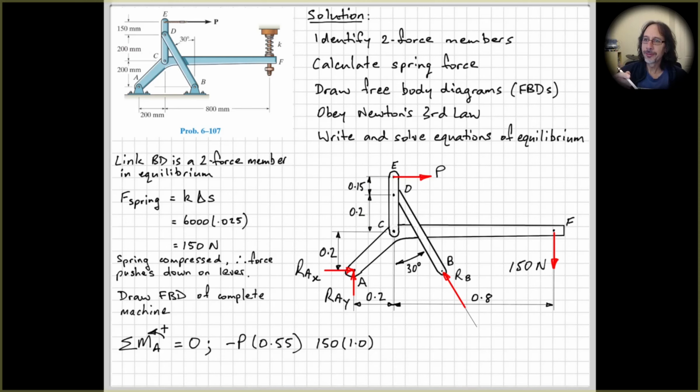So next, looking at the spring force out on the end here, we have 150 newtons times its perpendicular distance, 0.2 plus 0.8 equals 1, so put in 1 here. So even though the number that we're putting in here is 1, and it doesn't change the 150, get into the habit of actually putting in this distance that we're using, just so it's easy for the person reading your work to see what's going on in your solution. Right, so this is also negative, as we discussed before, tending to cause a clockwise rotation about point A.